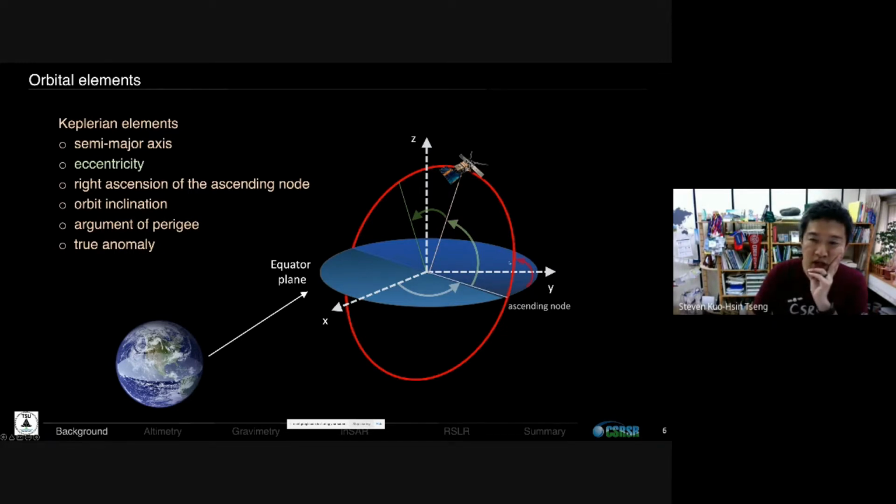It basically describes how high a latitude the satellite can measure. If a near polar satellite mission needs to fly over the polar area, then this orbital inclination is nearly 90 degrees. If we have a meteorological satellite and we just want to measure the tropical cyclones and so on, then we will probably design a satellite with a very low inclination. It's just flying around the equator all the time. It doesn't need to bother flying over the polar area. So that's the orbital inclination.